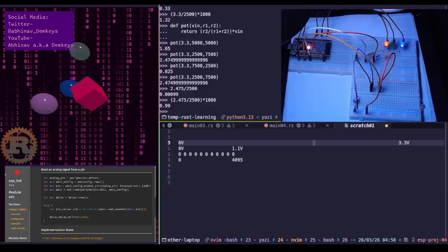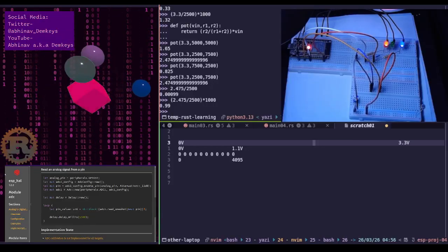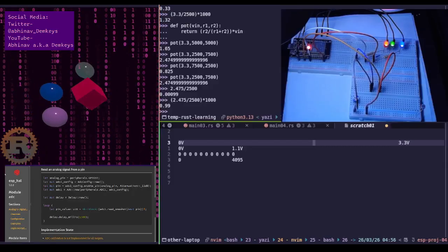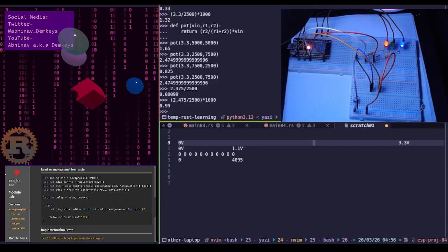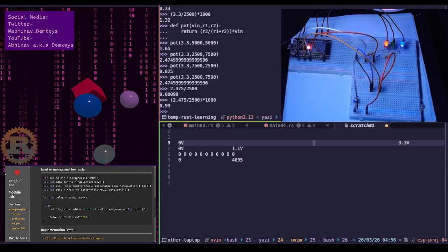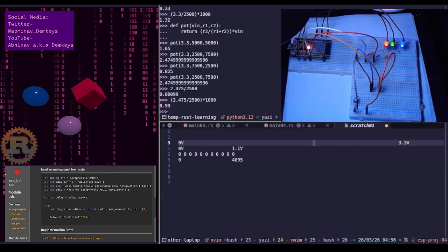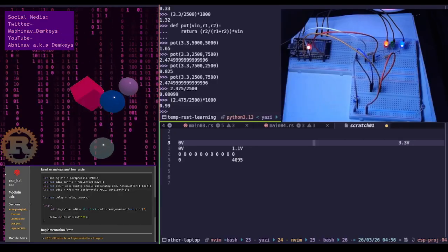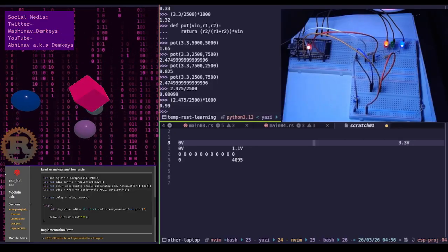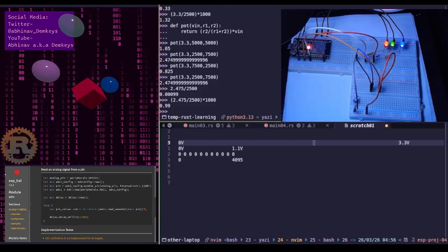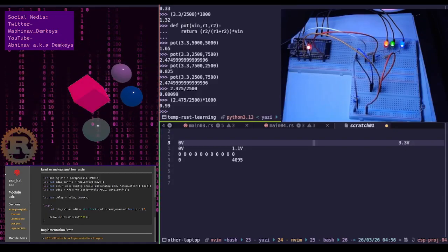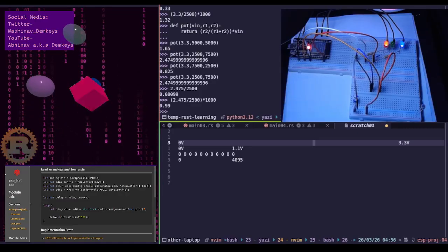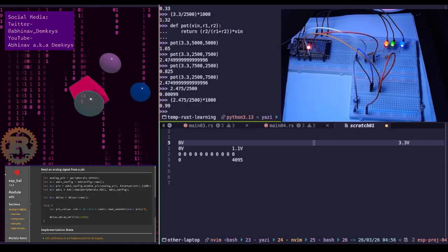A 1 mega ohm pot would get very jumpy, inaccurate readings because the current can't keep up with the ADC's sampling speed. The verdict: your math was looking at the resistance of the source, which is the pot, but for safety slash current draw into the chip, you must look at the resistance of the load, which is the ADC pin.